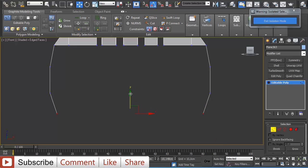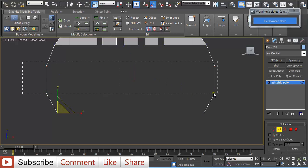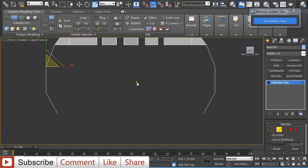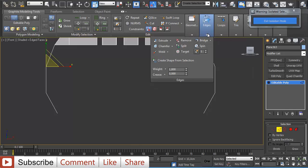And because these are fairly sharp, I'm going to select the edges, holding Alt to deselect what I don't want, and then hold Shift and chamfer them.